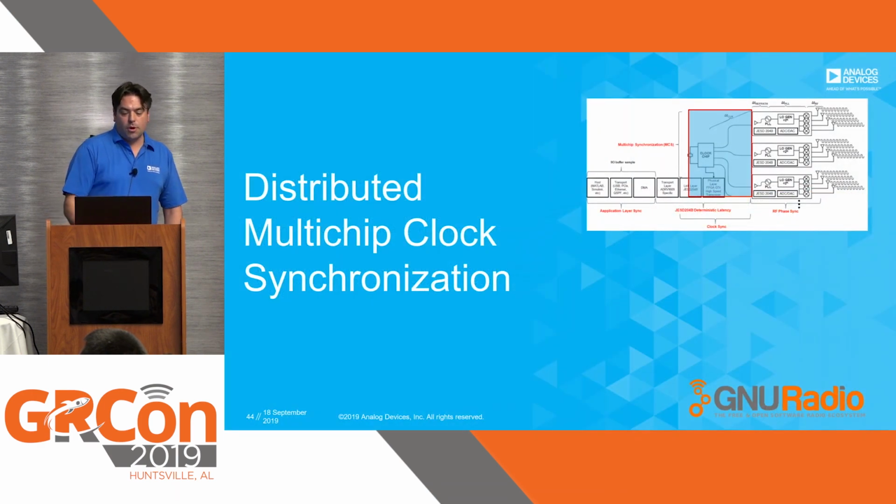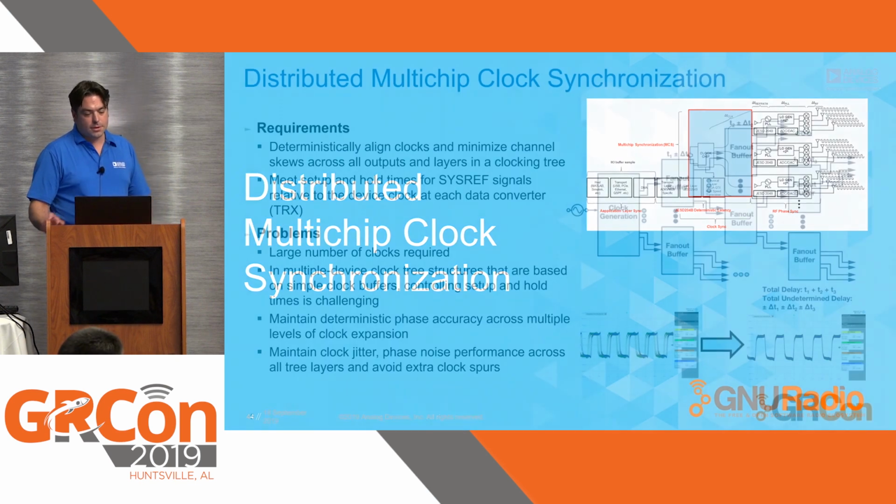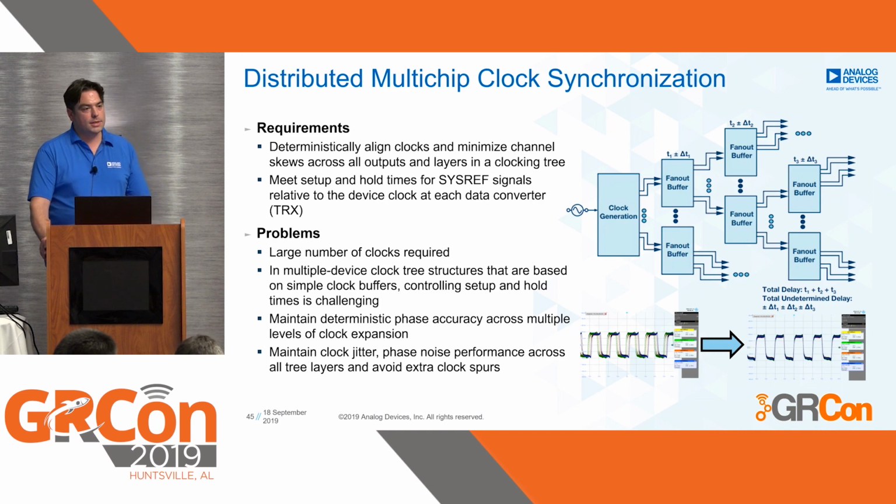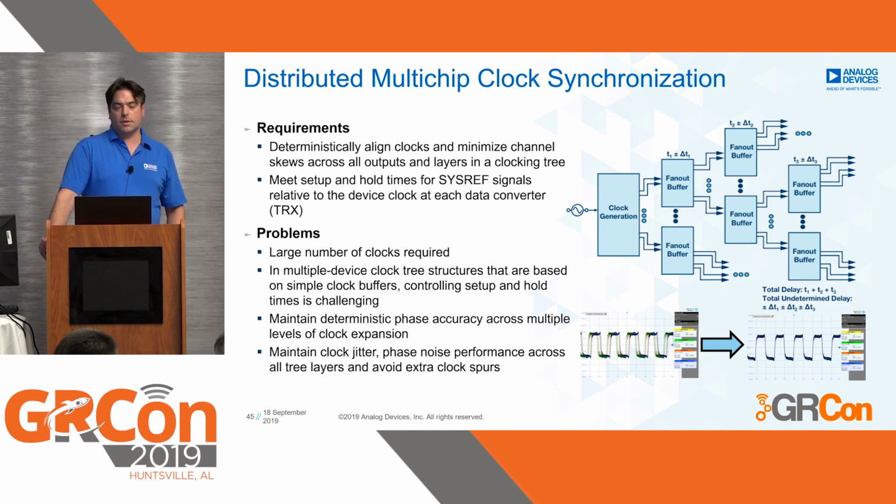So the last point here is the distributed multi-chip clock synchronization. What are the requirements? All clocks need to be aligned across multiple layers in your clocking tree. You also need to meet setup and hold for synchronization signals, such as SYSREF. The problem is, if you increase the number of channels, the number of clocks also increases in your system.